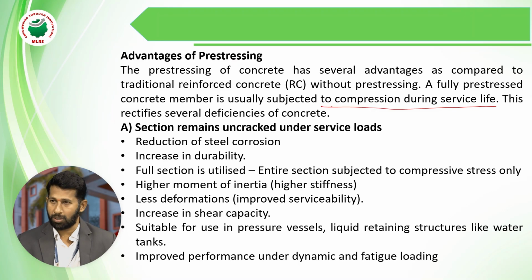Reduction of steel corrosion and increased durability. The full section is utilized, and the entire section is subjected to compressive stress only. Higher moment of inertia, less deformations, increase in shear capacity, suitable for pressure vessels and liquid retaining structures like water tanks, improved performance under dynamic and fatigue loading.